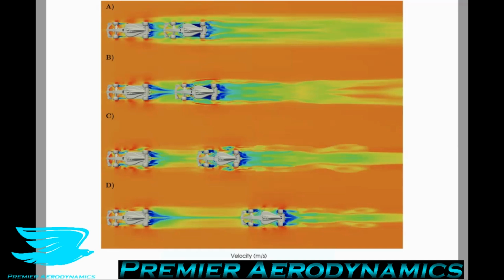So this is not just a bluff body, it's a body that has been streamlined. And that means that streamlined objects are not really as sensitive to that. There isn't as much pressure drag to begin with, and they're not as sensitive to these downstream effects because the flow upstream is still quite free stream, still quite nicely aligned. So that's probably why the upstream car is not affected nearly as much as the downstream car, or as much as cyclists in tandem, because it's a streamlined body. So the pressure drag for one is much lower to begin with. So we're not getting that benefit.